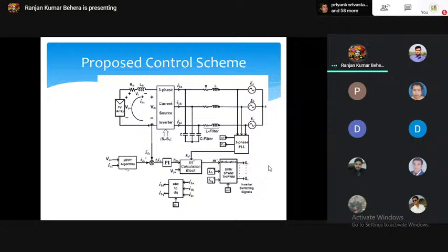First thing is, you need maximum power always. So for the MPPT algorithm, you can use this VPV and IDC, both measured by current and voltage source. Then with the MPPT algorithm, VDC reference and measured actual VDC go to this PI controller, and from there you will get the change in the voltage.